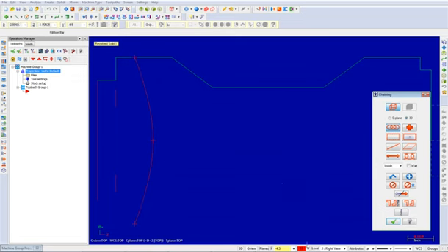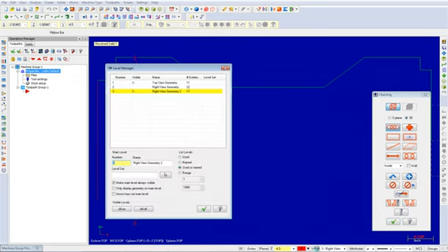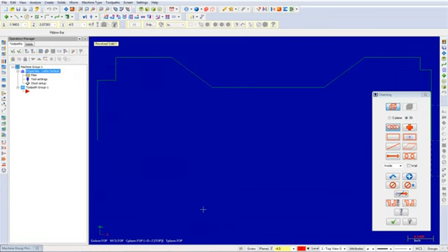Select Level in the status bar. Make Level 1 the main level by clicking on the number 1. Now select the All Off button. Select the OK button to exit the Level Manager. Make sure the view is set to Top View.